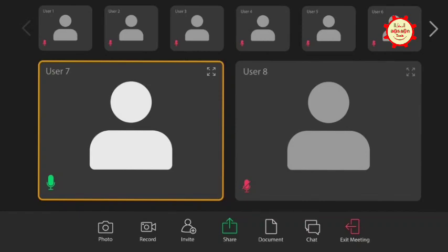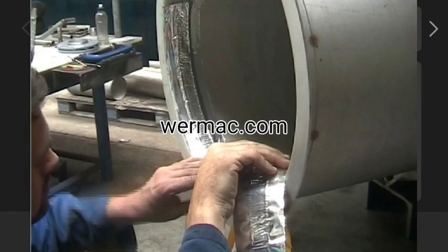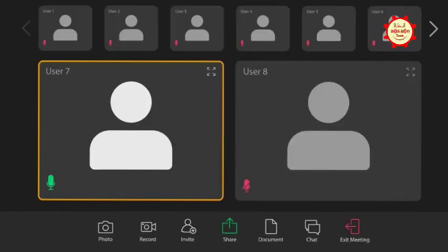Then for the backing ring, there is a gap of minimum 20 mm beyond the shell plane, bonnet side. Then the backing ring will start. Because the backing ring is in two split rings, we assemble it first. Then we assemble the floating flange. So there is a very easy practice in production. First you assemble the backing strip and the tube side, I mean the floating tube side things.